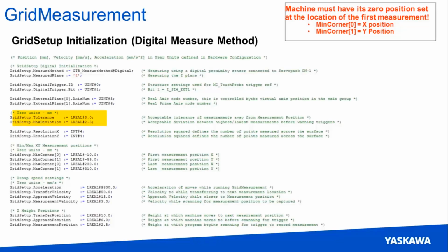So it won't error out as tolerance does, but it will at least give you a warning saying 2 measurements were this far apart, which in this case, if one measurement was 2.5 millimeters away from the previous measurement or any of the other measurements, it will produce the compensation warning on GridControl, just letting the user know that 2 of the points were quite far away.